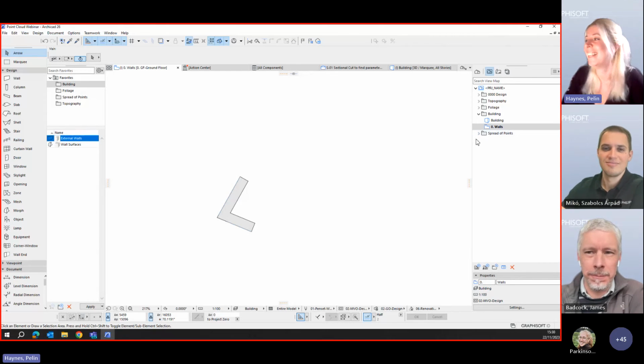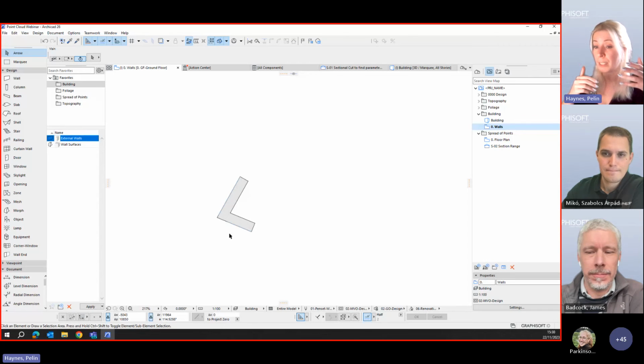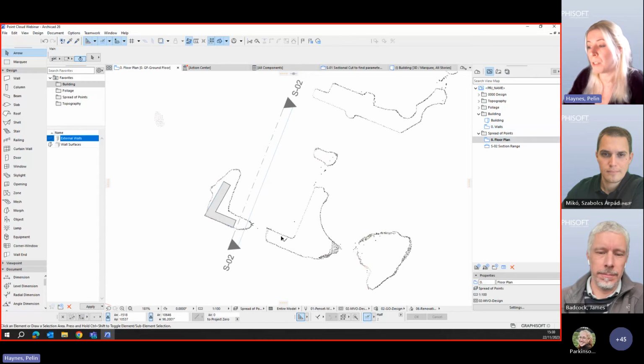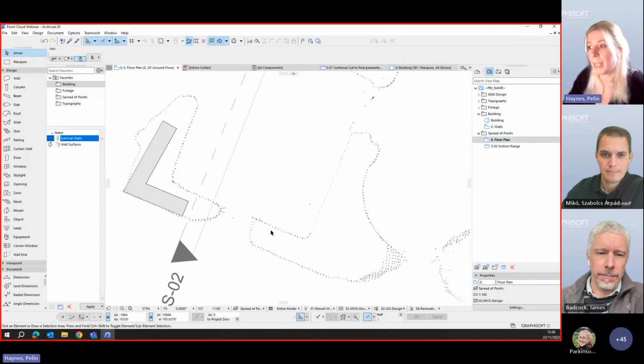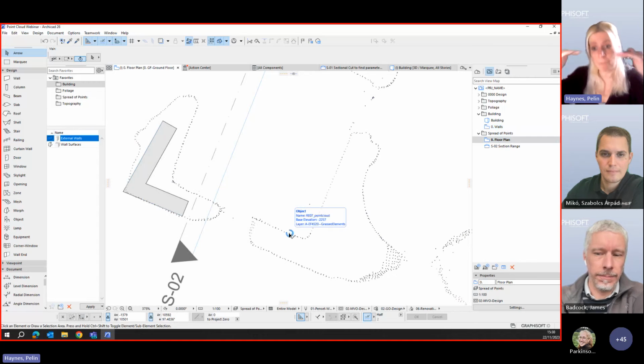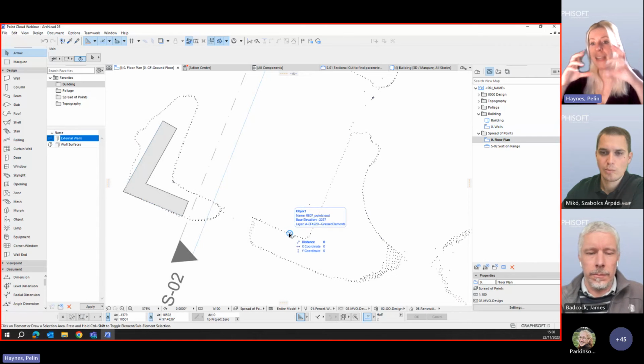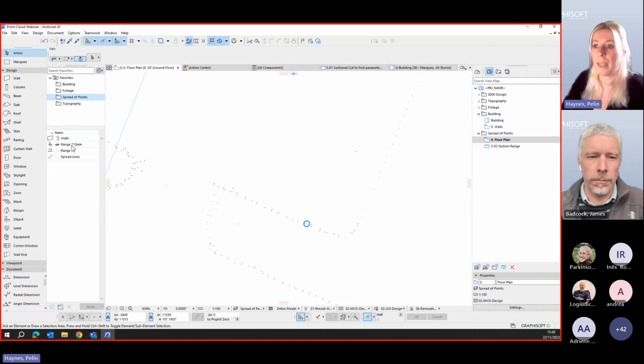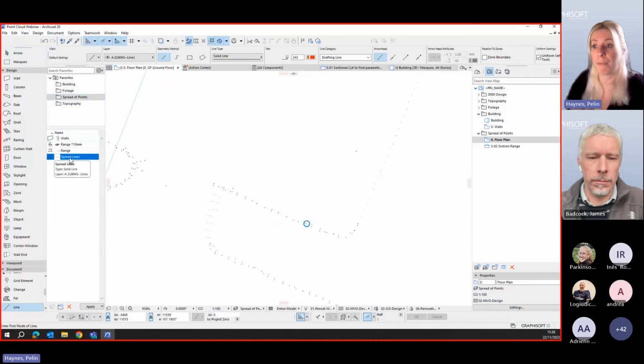Sorry about that. Okay, so the last tip is just spread of points. So now that we're talking about placing 3D elements, the location, the accuracy of those elements could be quite important. What I usually do is, once you receive your point cloud objects, again, depending on where you cut them from, arrange your cutting planes so that there aren't elements interfering with most of your external elements. And once you adjust your cutting planes, what I usually do is get the spread lines, the spread of points. I usually, from further inside to further outside, place 2 lines.